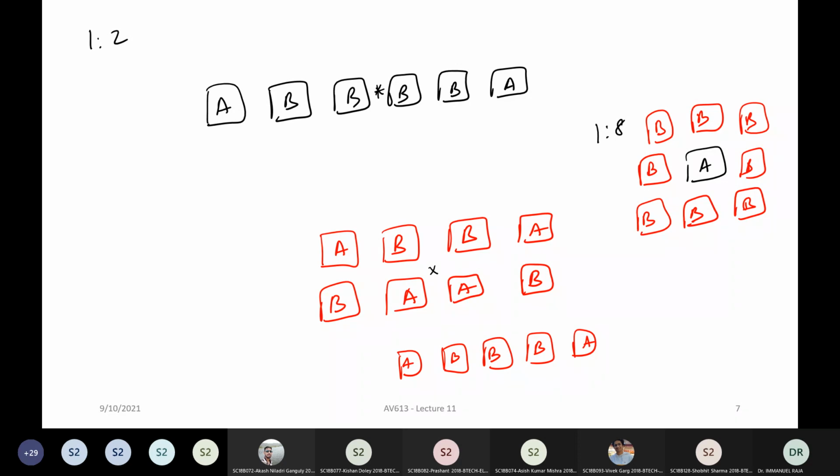I have a very naive question. How exactly are we trying to cancel out using this centroid theorem? You told that it is the linear doping concentration. Correct. So, for example, if you take this case, the VTH of this is going to average out, right? If you take the average of the VTH of this and this, and you take the average VTH, it will come to be the same because you have a linear gradient. You're assuming a linear gradient. Okay, sir. So we want it to be symmetric so that the VTHs will be the same value. Yeah.